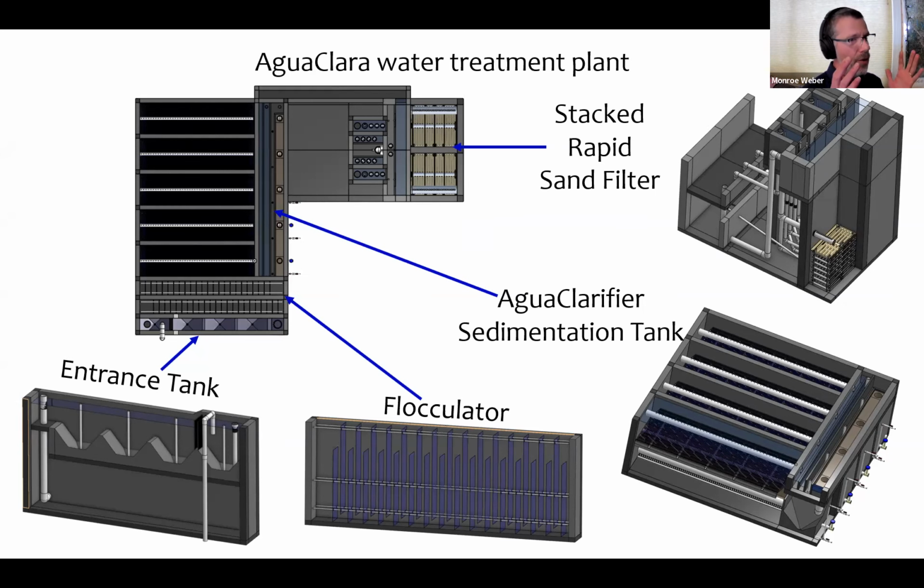Okay, so we're able to change the flow rate at the very top level and have all of these subcomponents update correctly and redesign themselves with that new flow rate. And I wanted to just illustrate what needs to be happening there. So way up high, for the plant design, up in the left-hand upper corner of our screen, and I'll show you where this is, there's a place where we can enter what we call overrides. And that's where we can enter in the flow rate.